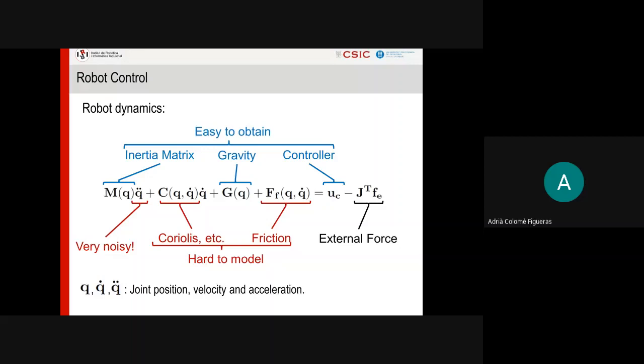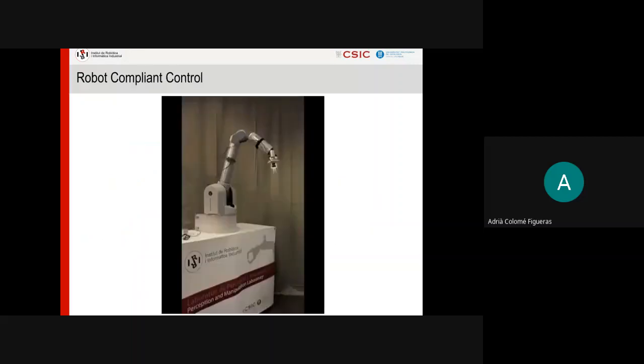So basically, the acceleration noise that you will have will be the position encoder noise multiplied by 1 million, and the reading will be basically a lot of noise and a hidden acceleration signal that you cannot actually read. So you have to be very careful with this situation.